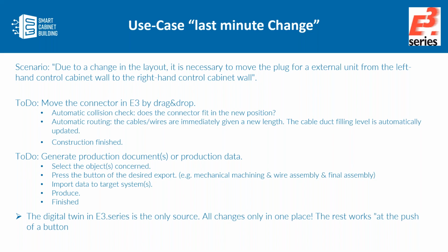Yeah, if you have designed this all in E3 and with E3.panel, it's just a small change. You do the connector drag and drop from the right side to the left side. It's automatic, if you can place this on the other side, we have done the collision check, so this fits, that's automatically checked. All the connected wires of this connector are rerouted.